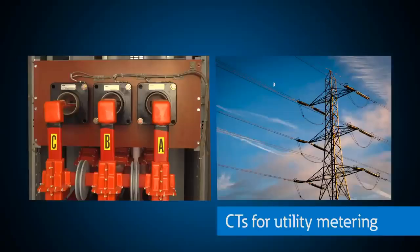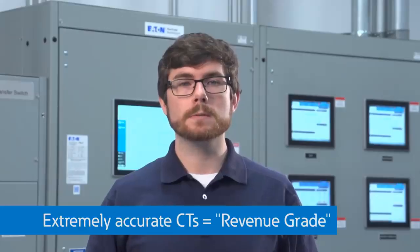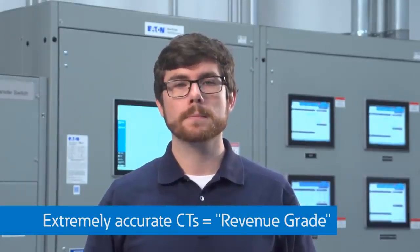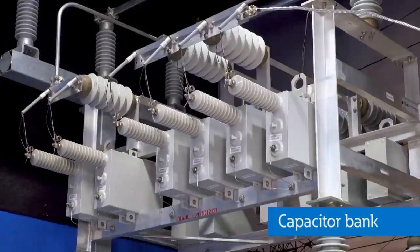For permanent applications of protection and metering, CTs can be found anywhere from generators to transformers to connected loads, or anywhere we want to monitor current flowing in the system. For example, utilities use CTs at their customers' incoming service to monitor the current and power usage for billing purposes. These CTs must be extremely accurate and are considered revenue grade since they are used for billing. Permanent CTs are also used to monitor power and power factor so that real and reactive power can be optimized.